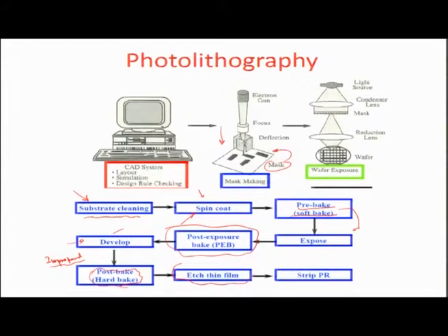And then you etch out the thin film, whatever you are using the resist as a mask for. For example, lithography is typically carried out because either you want to use it for a lift off process, or you want to use it for an etching process, and we must keep in mind that resists are normally always used as sacrificial material, unless you want to develop something with the resist itself, like a micro cantilever or something like that. So, you etch the thin films and then strip out the photoresist, so that you are left with the etch pits on the thin film that you wanted to etch. So, a resist would act as an etch stop layer in those situations. So, this is all about how photolithography is carried out in the laboratory.